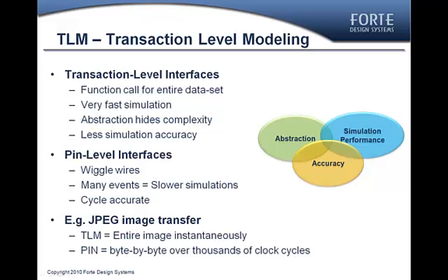When modeling at the transaction level, we can pass around entire coherent chunks of data via a single function call, rather than having to implement detailed pin-level handshakes to transfer that same block of data piece at a time. The key benefits here are improved abstraction and significantly higher simulation performance, since there are many fewer events in the TLM simulations. The penalty is accuracy of those simulations with respect to time, i.e. the TLM simulations are not cycle accurate.